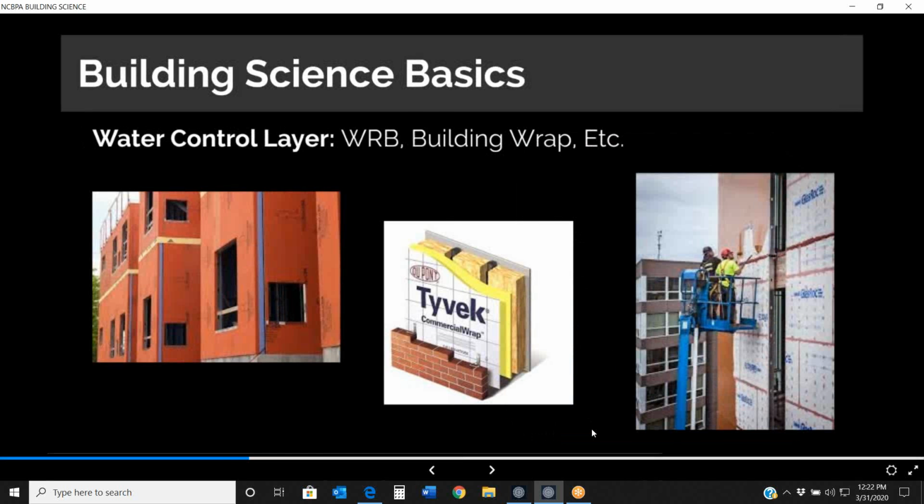One way that it was taught to me is to think of our control layers as a subway map. So all the different lines and routes running together. When we deal with punched openings or fenestrations, with tying in to roof conditions, we want all those control layers to tie in together. So looking at those control layers, our first one here is our water control layer.